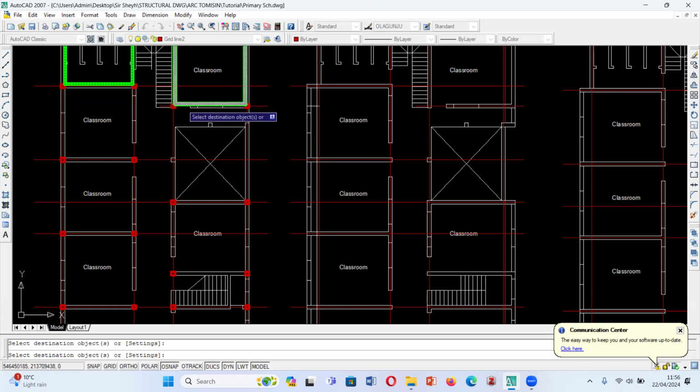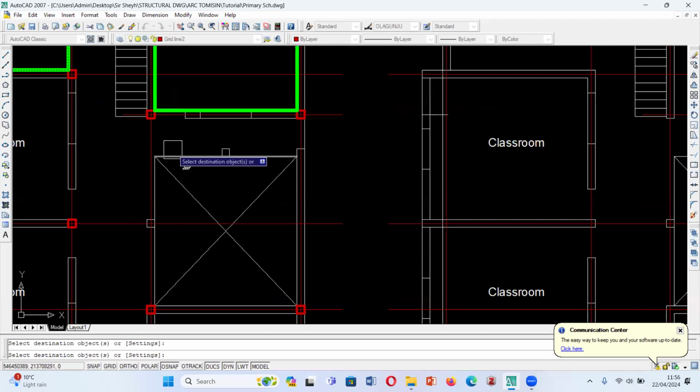But considering that there is a beam here normally, and there is a beam here, this would not make a cantilever. You can only decide to have a slab supported on 3 sides, or you throw a beam here, then you have your normal slab here. So personally, once I have my beam here, and I have a beam here, I can throw a beam here easily, even without the column, and have a slab here.